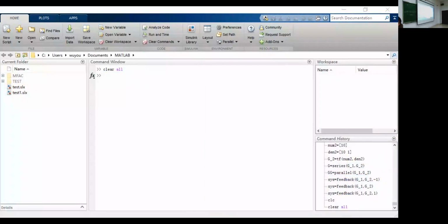Okay, we need a source, right? Let's try step here. Connect step into the input signal. So we have an input signal, it's a step signal, and we will have an output showing in a way of curve in scope, right? And by reading the scope curve, we can learn overshoot, the peak time, the settling time, or the time index we need, right?